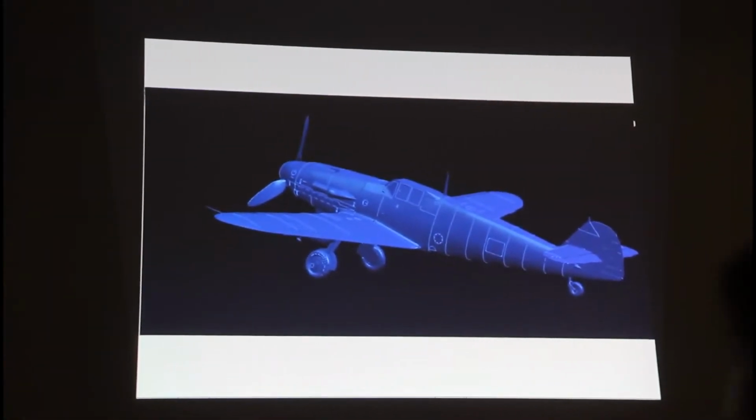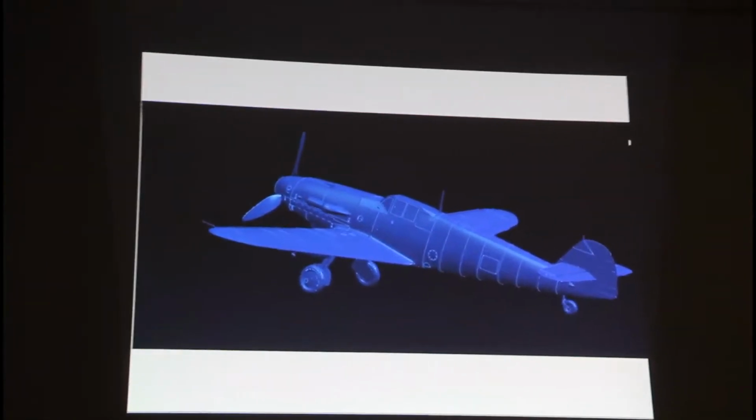Okay, it's very hard to translate. Clearance analysis. You must create a clearance analysis. Every part must have some tolerances. Some gap. It's 0.05 millimeters between every part. Why? Because of glue.